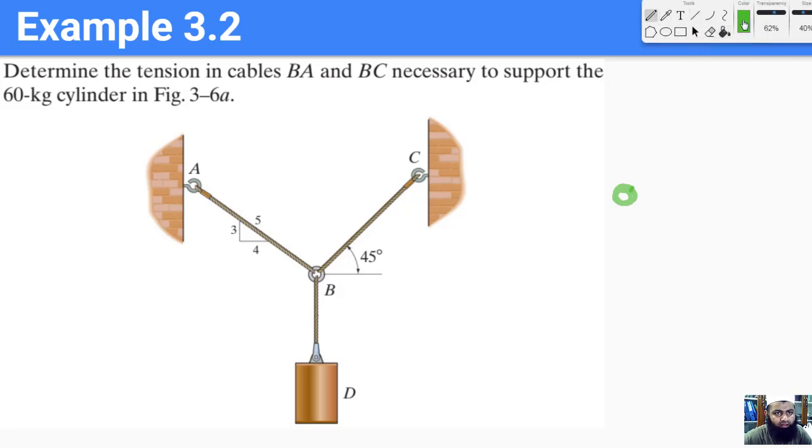Okay, and let me draw the forces with something like a red. The first force is the force due to this mass here, and so this is going to be 600 Newton. Notice that to be very exact, I should first draw a free body diagram of this block separately, and then the tension equals the weight, and then that same tension applies here.